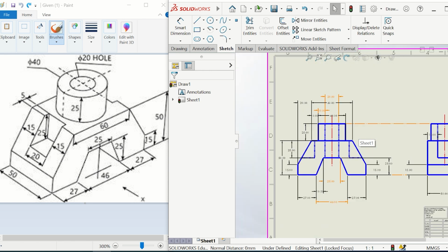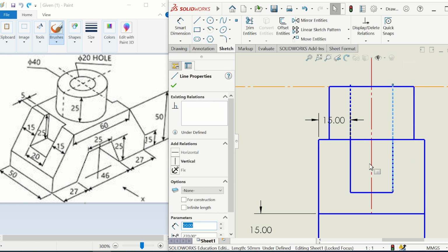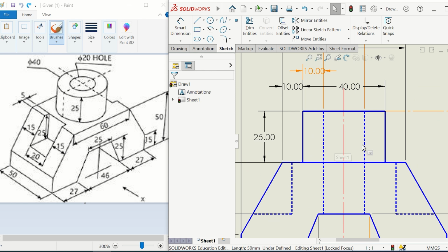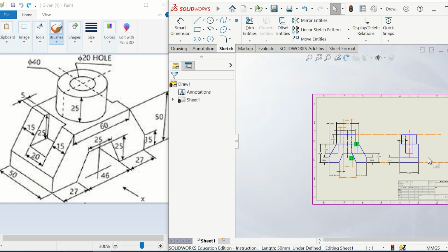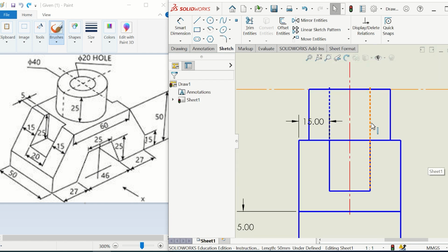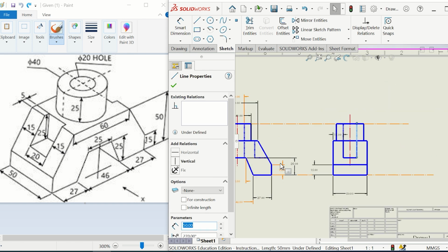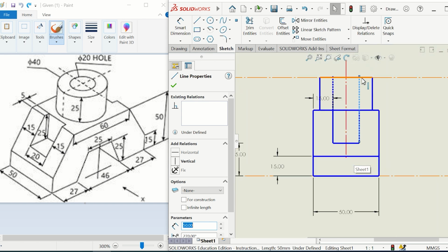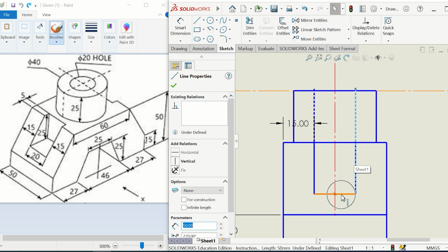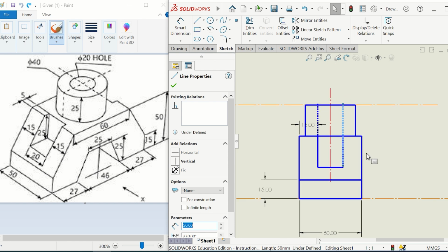projection of the hole. By the way, look at this line, exactly what I was explaining. In this view, this line goes hidden all the way downwards, because this hole goes all the way down as we agreed. Whereas in this view, it does go all the way downwards till it reaches the exit of the material, which is at this face here, which is aligned to this line here. However, this line is aligned to this line. However, there's exactly on top of it, and here you can see them in SolidWorks.